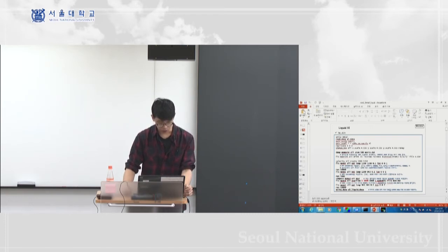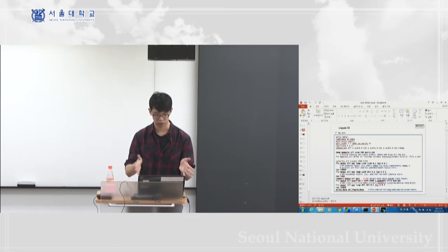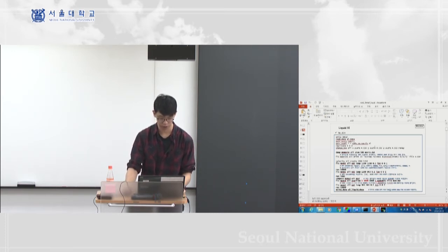So as usual, we're gonna use the EAM potential for aluminum metal, and we're gonna make a 3x3 supercell with the replicate command, because we're gonna need a larger cell to simulate liquid or amorphous. And then we're gonna set the lattice parameters, and then we will need this movie file later on to analyze the RDF.